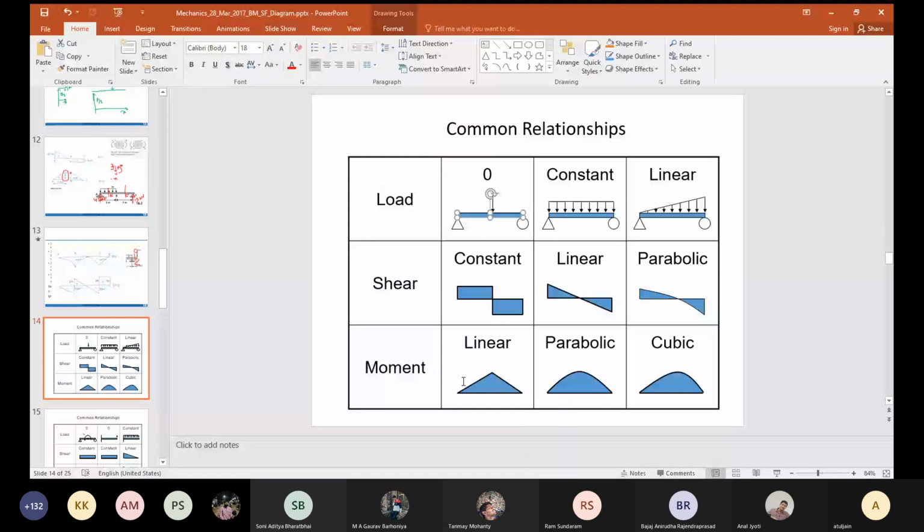5 times the radius because bending moment is increasing linearly as a function of length. Shear force is not increasing. So if my member is very small, mostly it is getting only shear load. If it is very long, it is only getting bending moment. And beams are members which are designed to take bending moments only. Therefore, we are making this statement that we'll call it a beam only if the length is significantly long. Clear? Understood, everybody?